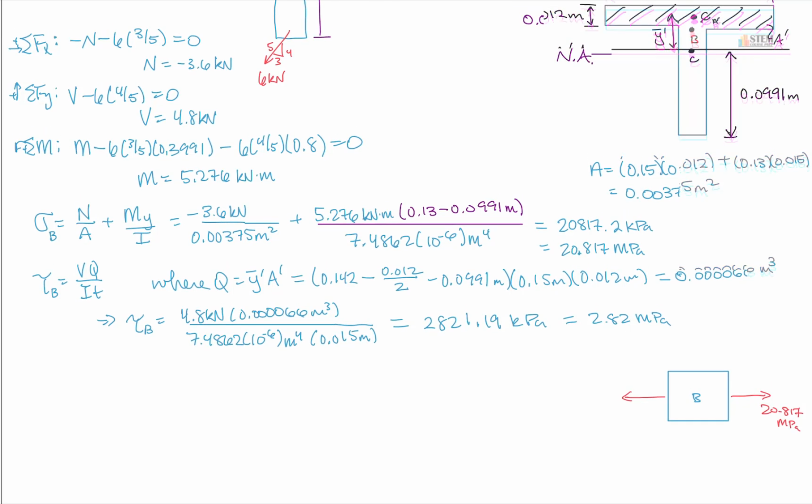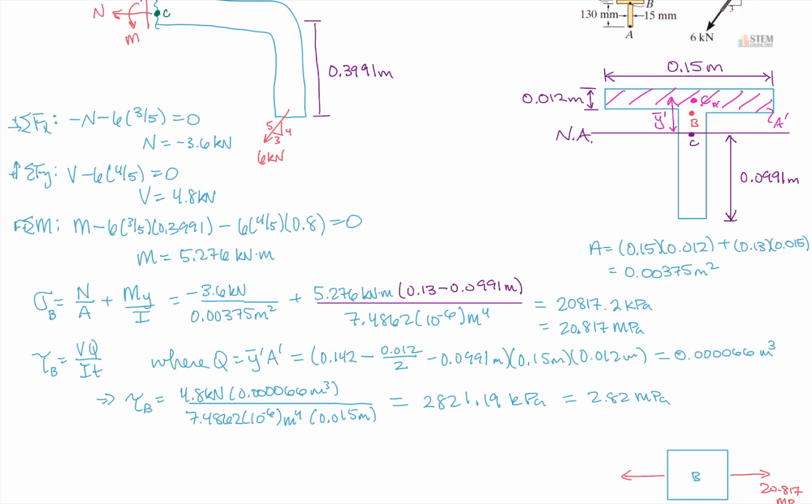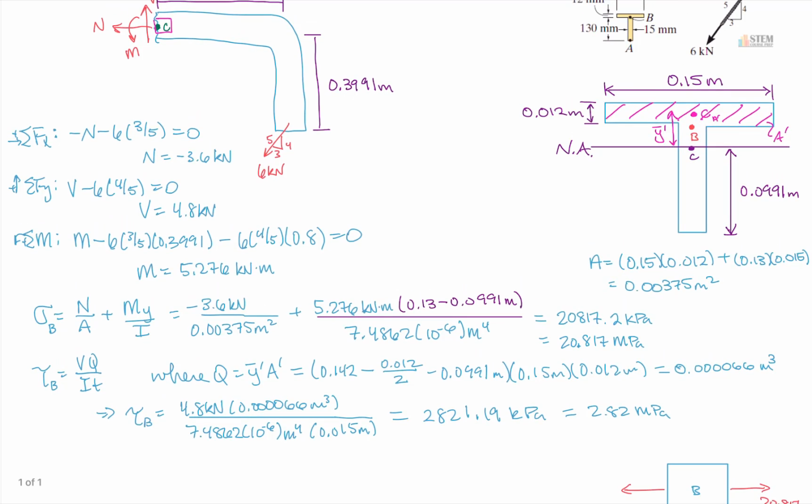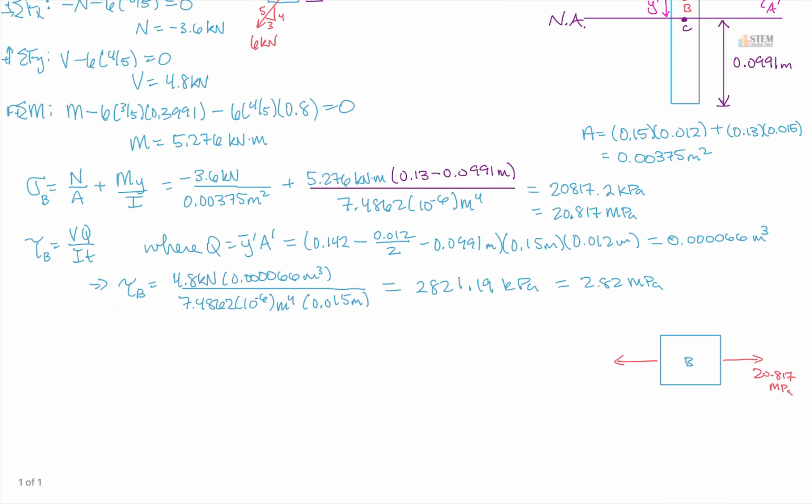And then I have to do the shear stress. The way I like to do it, I'm not sure if I'm the only one that does it this way, but I go to my free body diagram and take a little element and slide it in right where I did the cut, like right here. Then I see which way the shear is going on the face at the cut. Here I've got the face at the cut. Shear is going up this way. I had a positive, so it is going up. That means over here on this element I can put this one here, because this matches that face that was at the cut section. And then, by the complementary property of shear, we have to have one going down here, and then one here and one here. This value would be 2.82 megapascal.